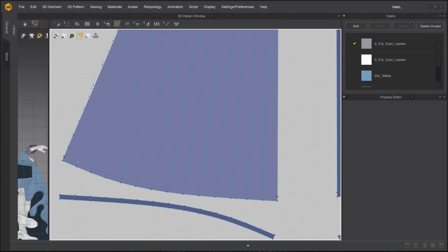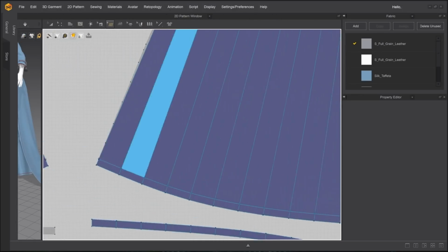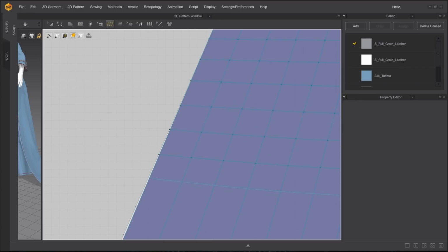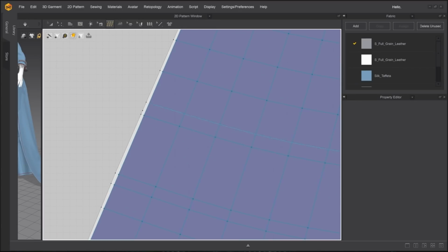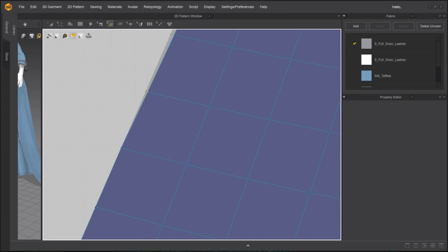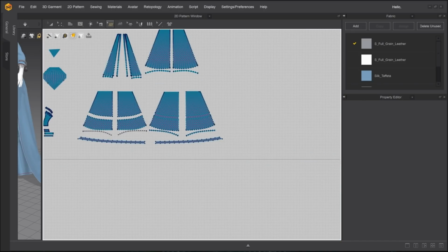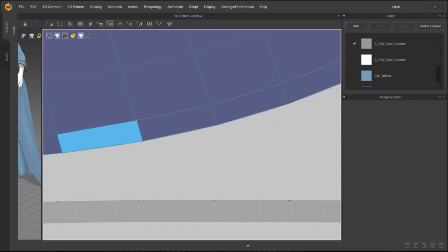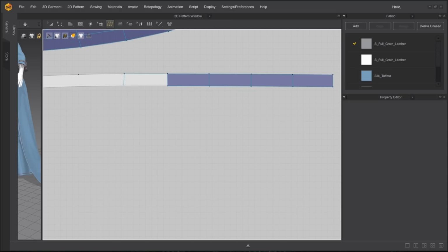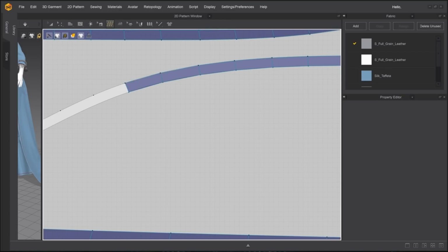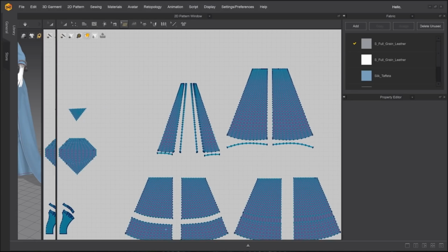Then I repeat the same steps for the back pattern using the Create Topology tool and the Control and Shift hotkey. I drew these rows as closely as I could to the ghost points from the previous pattern, but I still need to snap them into place. Following that, I'll just do some general cleanup and finish drawing topology on the last piece of facing. And having finished that, the entire garment has been covered.